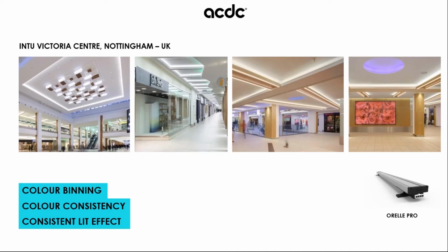So when you're specifying your luminaire, think about color binning, think about two-step macadam, so that you're getting that consistency from one cove to the next, from one luminaire to the next, from one LED to the next. It's absolutely critical for the success, the look, the feel of this environment.